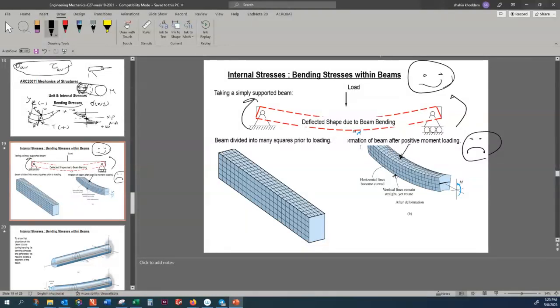And right in the middle, I mean the neutral axis. The neutral axis for a rectangle is right in the middle. If that's a triangle, the neutral axis is 1/3 from the base, 2/3 from the apex. If that is a circular cross section, you have to find the center of area of the cross section, and your neutral plane passes through here.